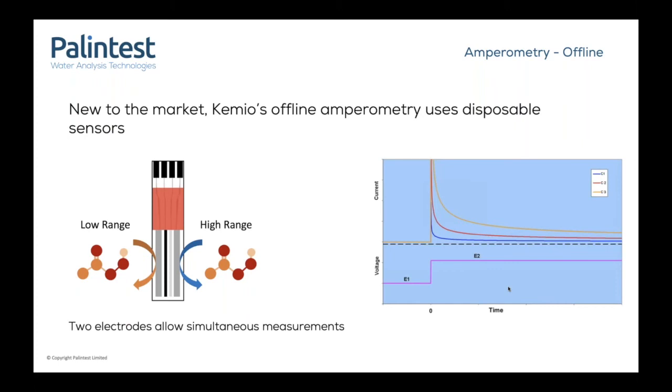So single use means you're changing the measurement surface every single time. Now you don't need to worry about fouling. Now there is no calibration to drift because it's a brand new sensor every single time. So we really have overcome the fundamental limitations of amperometric probes that you see in food and beverage situations.